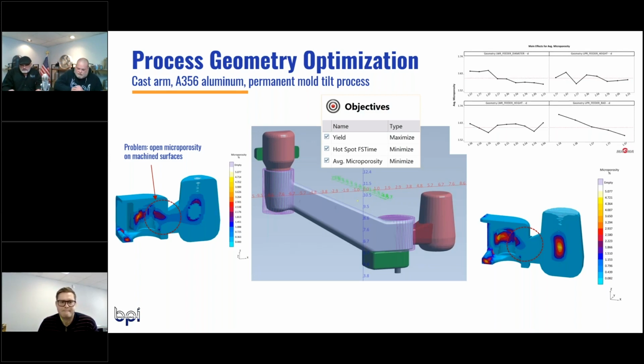Well, it's all based upon the design of the part, Tim, to be honest with you. As he's doing there, there are multiple different yields that you can get through that animation, but there are certain things you just can't get away from, and thick sections are one of those. If I was to throw out a rule of thumb, probably looking at part weight times 2. It's not always double, but that's why, in this simulation, he's showing that you can optimize the yield on your casting. So it may not necessarily be 2, it may be 1.5 times, which is a lot better for everybody in the long run. And that's what he's doing here. And I think he's running through the 80 different variations to see what is optimal.